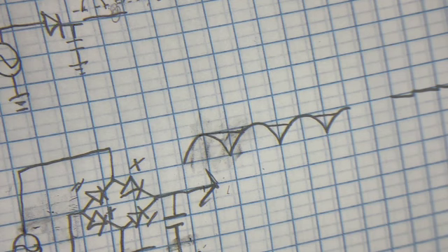And that's the basic diode. Now, I'd mentioned there were other diodes. I mentioned Schottky diodes. Schottky diodes would never be used for this because of the low forward voltage. And when you put reverse on them, they don't block the way that these do. So they're really fast and they adjust to the current really well, but they are used more for blocking a DC from going into reverse than they are for rectifying.